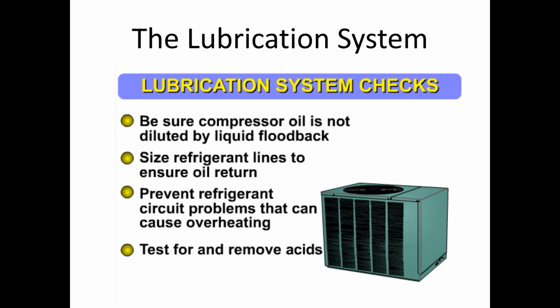We want to make sure that our suction line is sized appropriately according to our line sizing chart so that we get the oil back to the compressor.